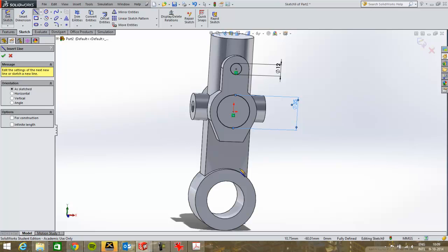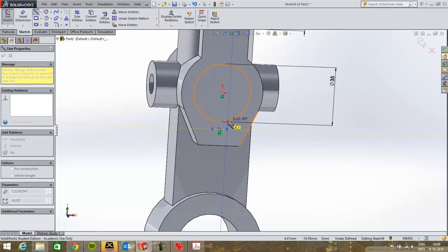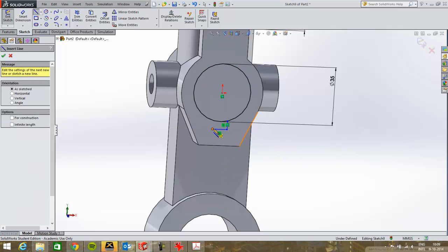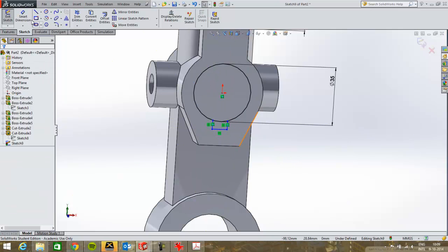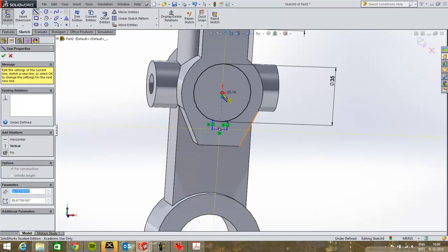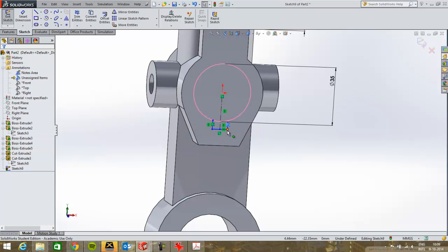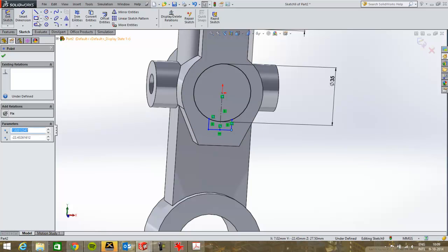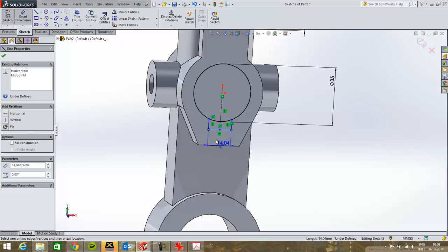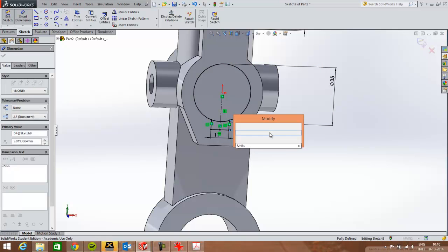So the dimensions are again on the drawing. The width of that is 11, so I'll just create this and this. And now it's easy to get it in exactly centered by using just a center line from there to there. And if that center line is exactly vertical, then this thing is exactly in the middle. Then I'll enter the dimension of 11 and a height of 6. If I'm correct, yeah, 6. This dimension is given in the drawing, 6.